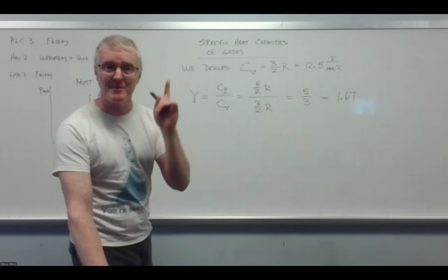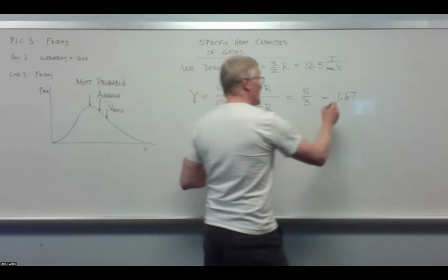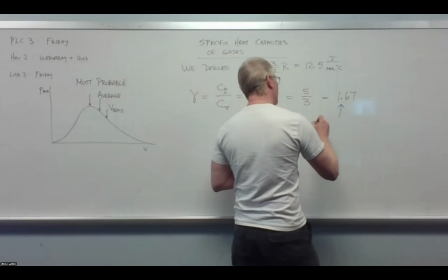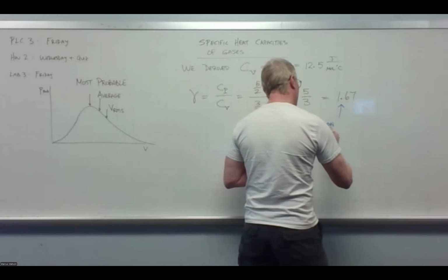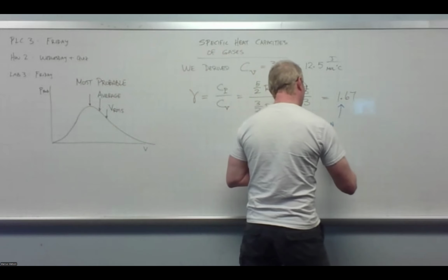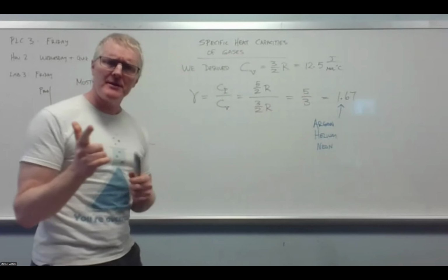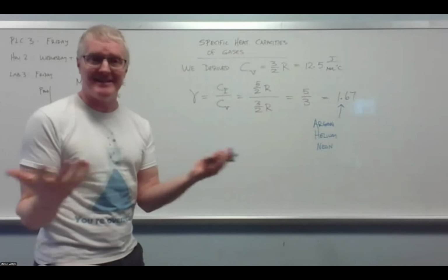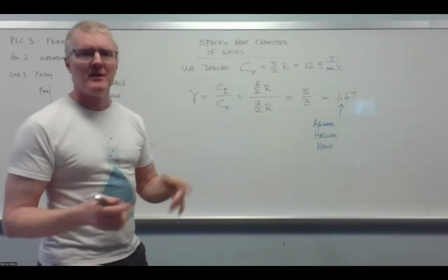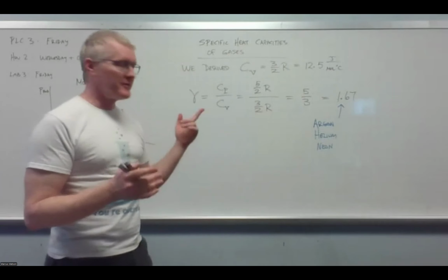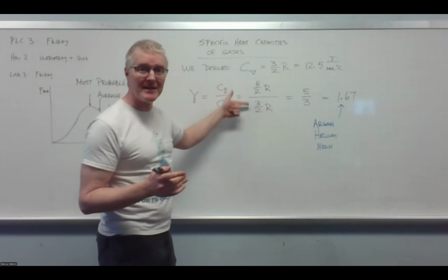That K number is this gamma value that I just defined. So if you looked at some of the gases, the K value works out great. Argon worked out really well. Helium worked out really well. Neon worked out really well. They all had that. But then I got into gases like carbon monoxide. It wasn't this. Why was it not this? Because the ratio of the two specific heats was not the same as what we have here.